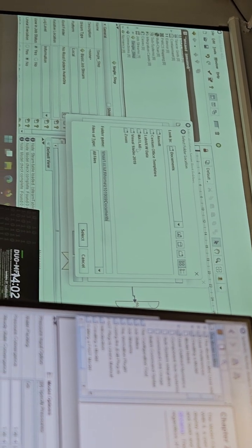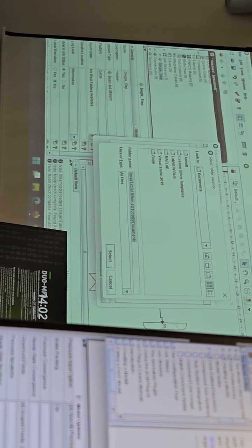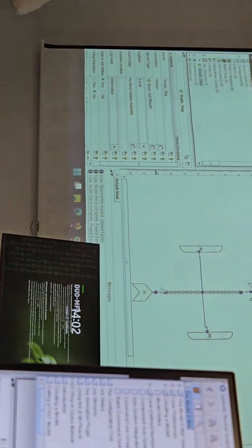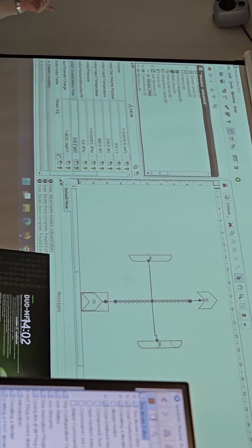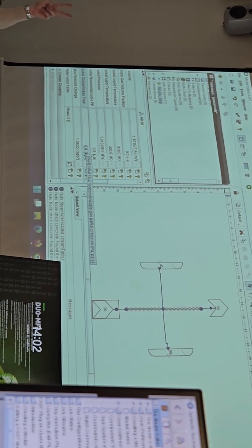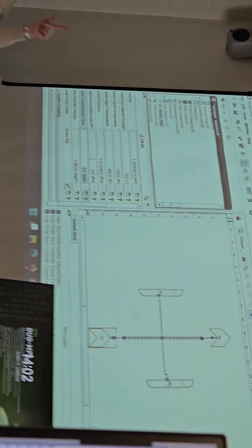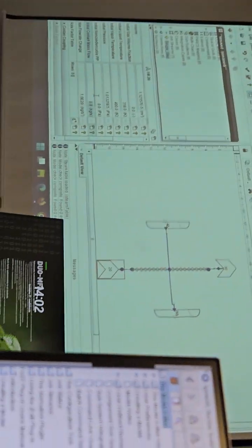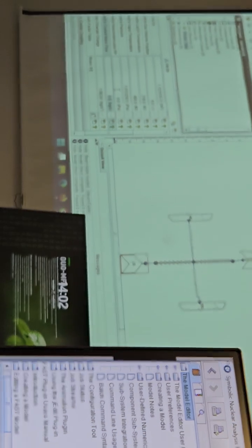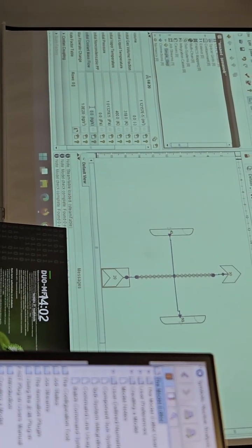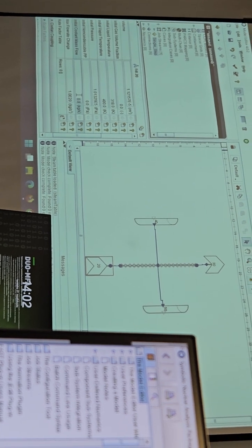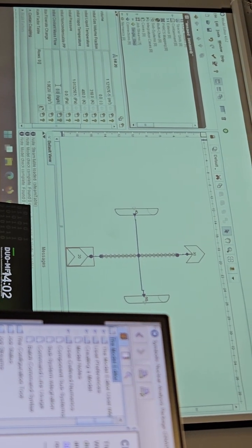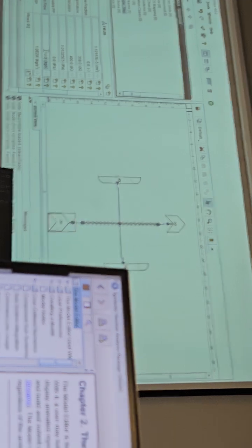So where do we input the coolant mass flow? Is it from the fill? Yes. One thing I really forgot to define is in the fill component, here is the initial coolant mass flow. There are two options. You will have to provide two simulations with different mass flows. It is in grams per second, and just convert it into kilograms. And run two cases and analyze them. So we just change it in the initial coolant mass flow? Yeah, initial coolant mass flow, because it's constant.